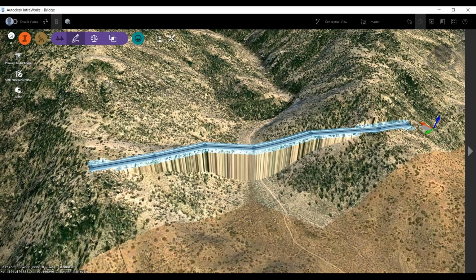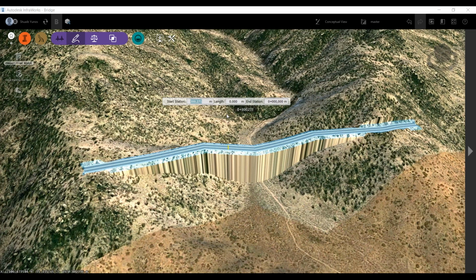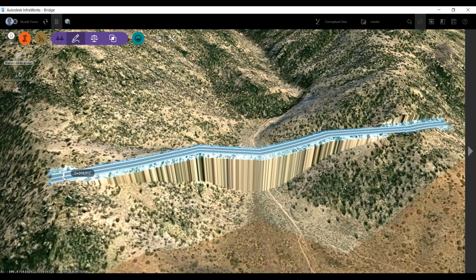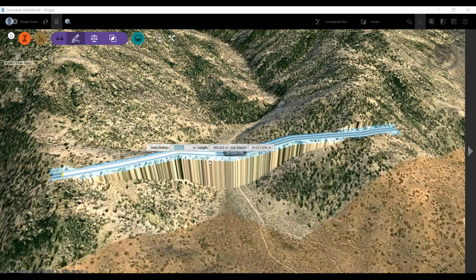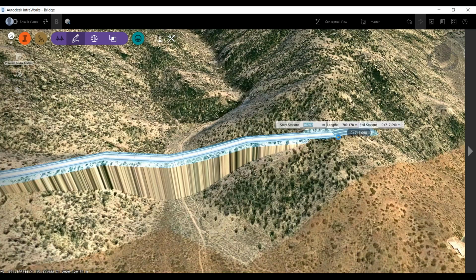And you've got these types of bridges. Of course, you've got precast and you've got steel. I'm going to be doing a precast one, so I'm going to click on precast, and it's going to ask me to define along the road. This wouldn't work if you don't have a road in. So I'm going to just do a nice one. I'm going to define it maybe till somewhere there. Once I've done the start to finish of the road, you're going to see it actually generate the bridge for me.